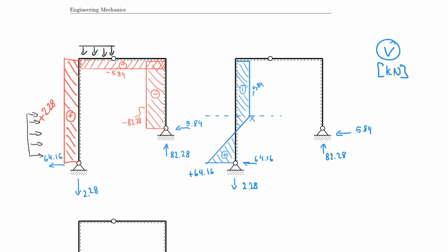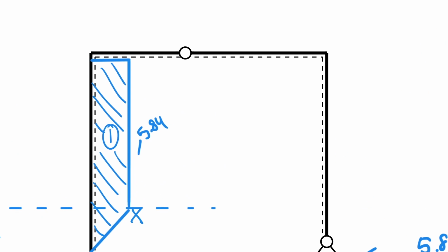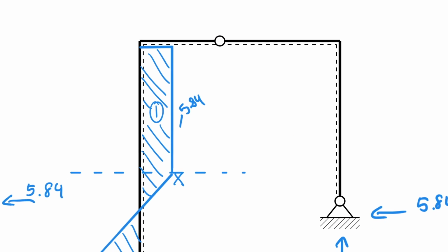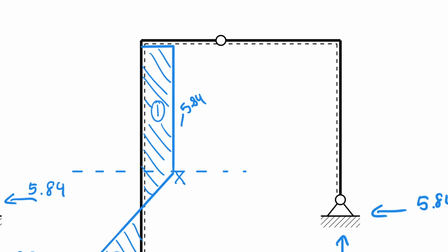So now it becomes interesting because we have to do the very same thing for the other direction. And I guess it's easier if I zoom in here. So I have to first go down now. So I'm going to focus on this horizontal member here, the entirety. Remember, there's an evenly distributed force here. So I am going to first follow my arrow, which is the support reaction on the bottom, which was negative 2.28, or it will be negative 2.28.